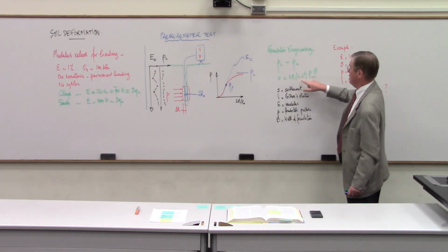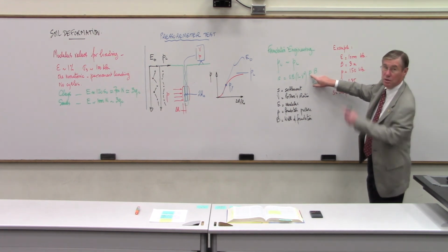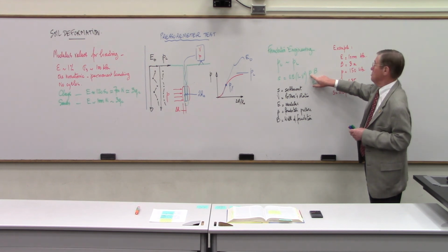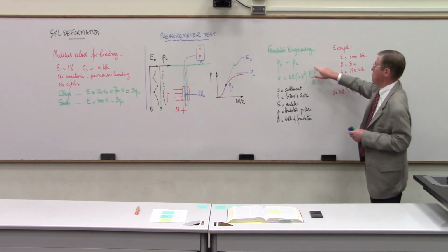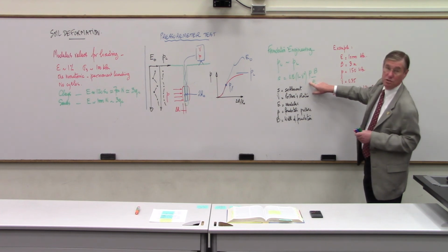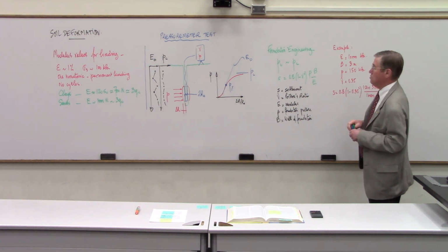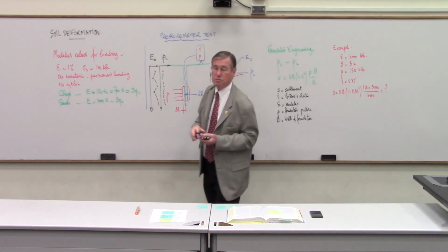And then you have 0.8, you know Poisson's ratio. The pressure is going to be the load divided by the area, so B squared, let's say if you have a square footing. So load divided by B squared multiplied by B, we have load divided by B. And then E is here. You know the load. B is the unknown. And then by design, you can calculate B to be able to satisfy the settlement that is required in this case.